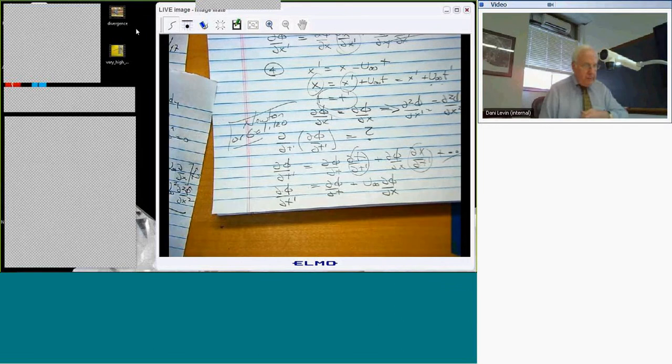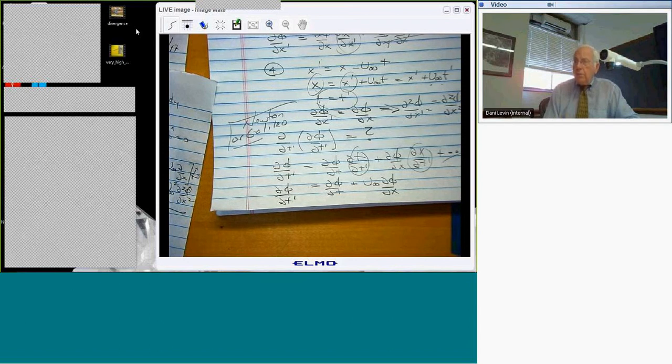All right. Okay. So what have we done? We've traded the simplicity of the field equation for a more complicated field equation, in turn to get an easier way of applying the boundary condition, because now we're in the body fixed boundary condition and we know where the boundary is. We're in that coordinate system, right? Otherwise, if we're in the fluid fixed system, we'd have to keep chasing the body to apply the boundary condition, which is not a good idea. Okay.